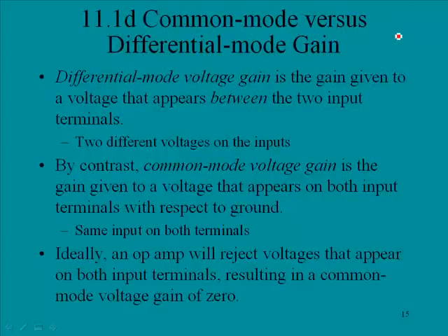Okay, we're concluding section 11.1. We start out with a discussion of common mode versus differential mode gain. Differential mode voltage gain is the gain given to a voltage that appears between the two input terminals. It represents two different voltages on the inputs. Recall that a differential amplifier amplifies the difference.